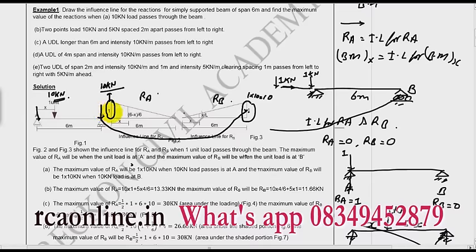So what we have to do is multiply the ordinate for the one unit by the value of the load that is passing. So the simple rule: if it is 10 kilonewton, it will be multiplied by 10. If it is 20, then I will multiply by 20. If it is 0.5, then I multiply it by 0.5. So simply, we can find the maximum value of RA and RB and also the condition when this will happen. Both things we can find by influence line.